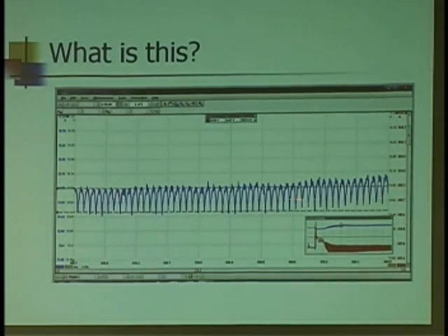What do you think I'm looking at here? AC ripple. Yep. That's the AC component. Isn't that what an alternator puts out? Unless it's rectified. And what I'm truly getting are the clipped tops of the positive side of that AC voltage.